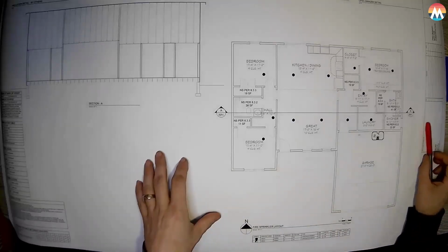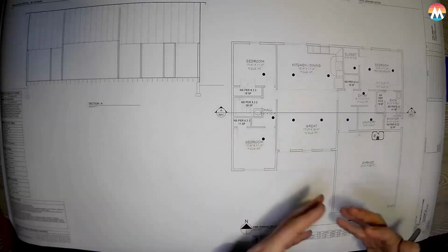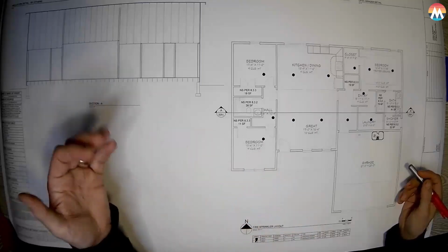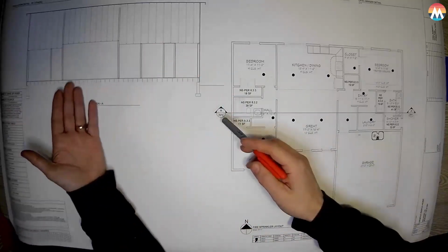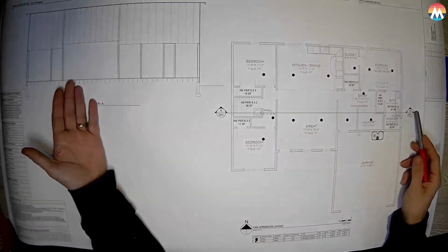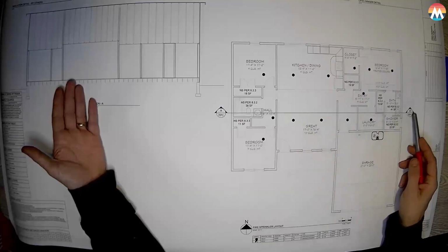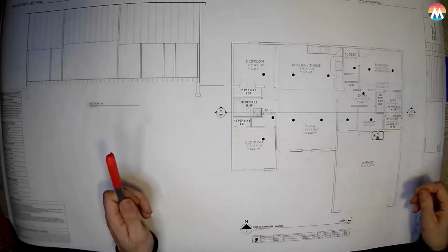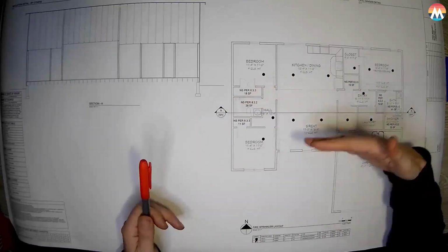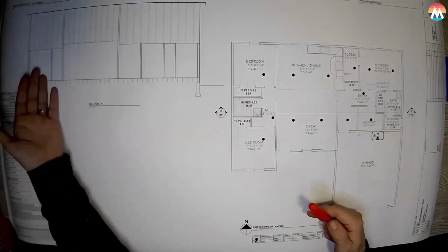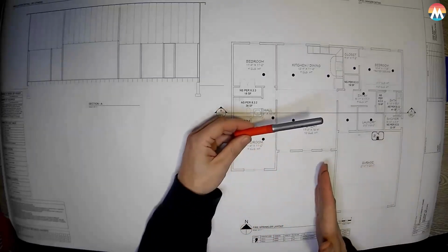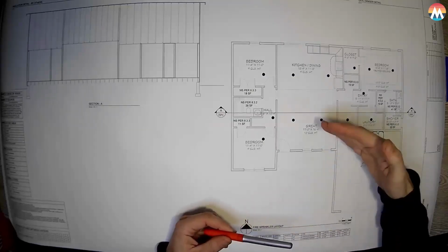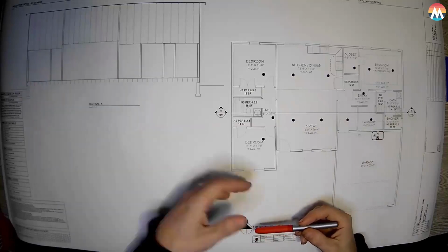The reason I wanted to mention the cross section is the technician doesn't know which direction to run the pipe. So how do we know which direction to run the pipe? Well, this section over here is at this location on the drawing. This is the call out for the section. So what that means is if you were to imagine that this house was a cake and we had a giant knife and sliced the cake across this line and pulled it away, this is what we would see into the cake. If we were standing here and this part was pulled away, that would be the view.